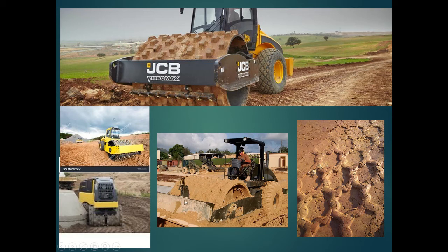Okay. Obviously, the soil is a little bit too wet here. You can see this machine is buried. So what we can do is, one, dry this out, or we can increase the size of these compaction equipment, these sheep's feet here. Okay, so this is cohesive soils. See, we're kneading it together.